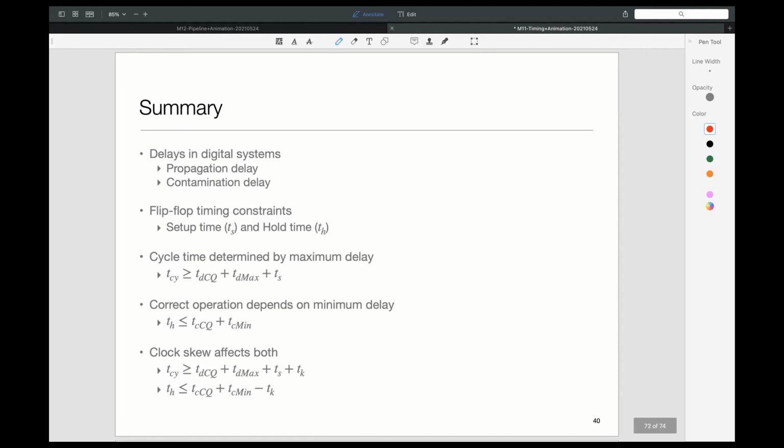So, clock skew affects both. If you have control over the clock skew, the way you are wiring, maybe you can even use it to your advantage. But generally speaking, you have to be prepared that clock skew can hurt you, because what happens is we design our hardware in these high level tools, and then we get a schematic, and then we use some other set of tools to place the parts on silicon and wire them up.